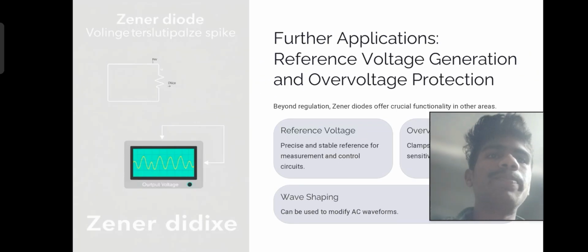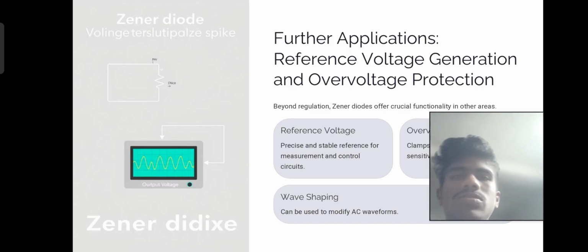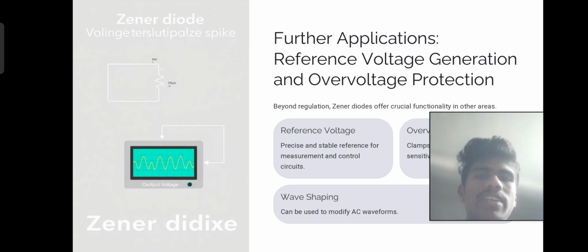When the PN regions are heavily doped, direct rupture of the covalent bonds takes place because of the applied voltage. This process creates a large number of electron-hole pairs, and the newly created electron-hole pairs generate a large reverse current.